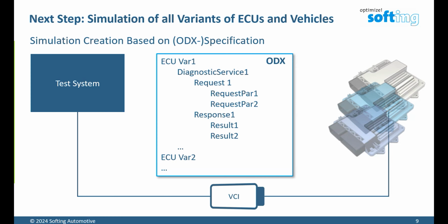That is one thing. The next thing is the ODX file itself is available earlier than the real ECU. I'll make an example. The ODX file, because it's a part of the development of an ECU, is, let's say, available on the 1st of March and the real ECU on the 1st of June. So we had this dilemma in the beginning of the presentation: how to make the tester available, completely tested, when the device under test comes later.